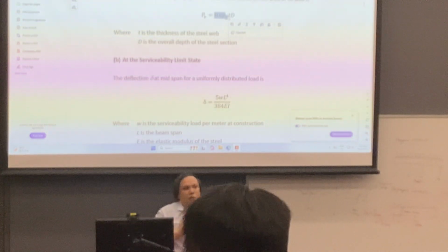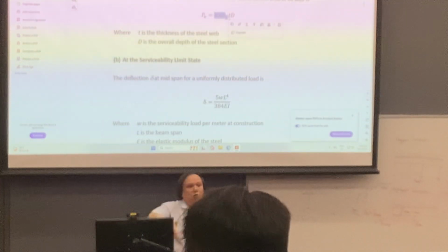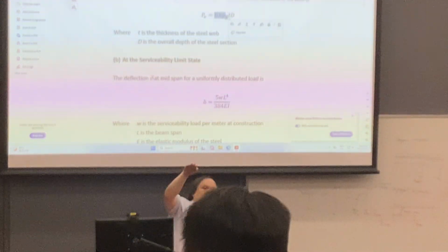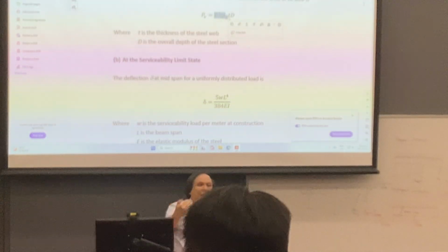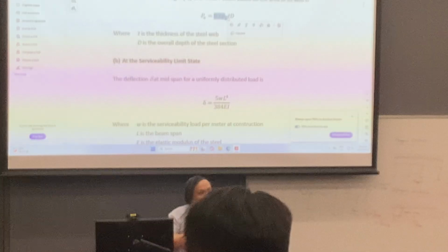So this one actually just shear, because it's the vertical direction, so just the vertical part, the web part will take the shear, and then for the bending moment, because you have compression and tension, right? So the top part and the bottom part will help to take the bending moment, okay? So just use this simple idea. You can always memorize the importance of the flange and the web, okay?